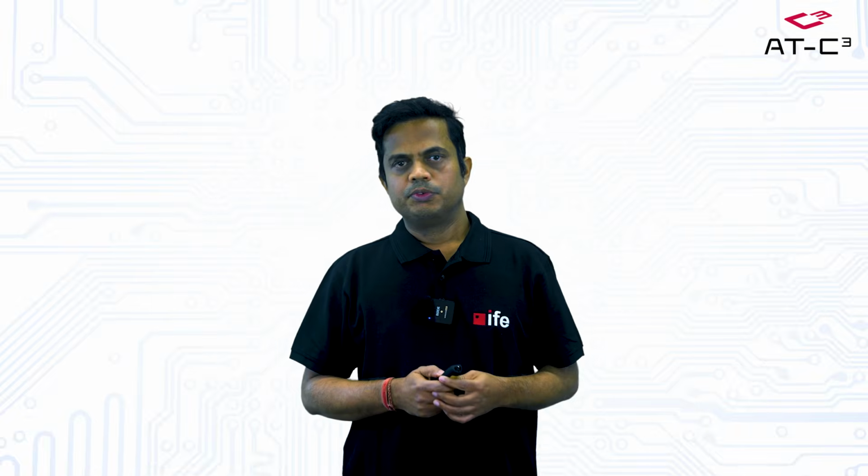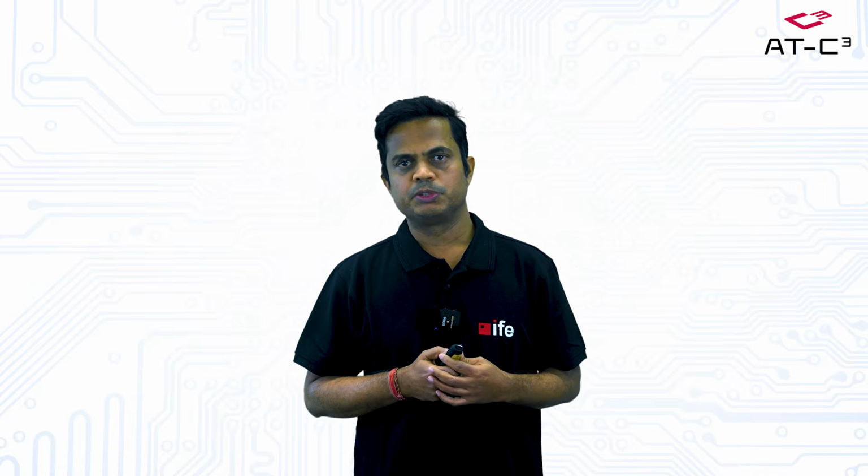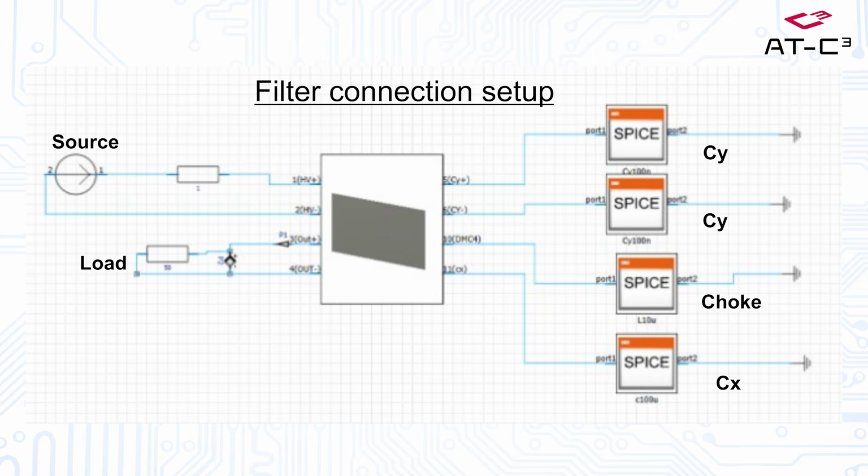And now we'll see the field simulation. In this case, we have used CST for our field simulation. This is the filter structure. You can see this is the plus and minus line. We have a Cx capacitor here, the choke here, and two Cy capacitors here. We'll extract the parasitic behavior of this filter using CST. The extracted parasitics of the traces along with the components have been attached to the schematic.